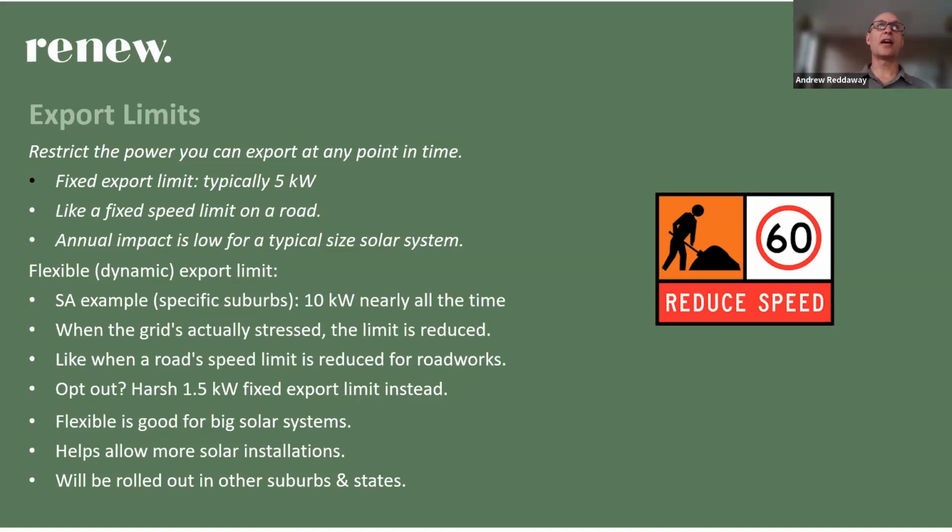So let's say you have 13 solar panels on your roof. That might be a total rated power of, say, 6 kilowatts. Now, the thing there is that's 6 kilowatts rated at laboratory conditions where the sun's at just the right angle and it's full sunlight, there's no shade, there's no clouds, the panel's not too hot.